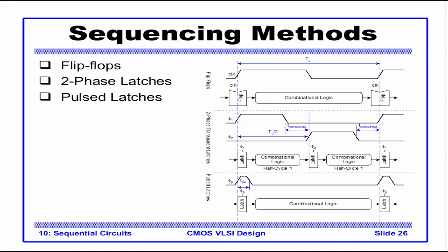Although design wise latches are simpler, in the sense that construction wise they are smaller, when we want to use such elements in our design, flops are much simpler to handle, the timing relationships are much clearer, and the clock network is much simpler compared to latches.